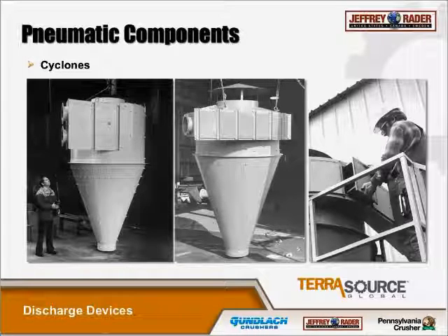These cyclones, just as with the valves and the elbows, are designed to have a low impact inlet section that allows you to minimize material damage, eliminate buildup, and get longer service life, easier maintenance, all the important things. Got different options. You can do multiple injection as shown in the photograph on the left. You can do right hand, left hand inlet. You can replace body liners, though most people just choose to replace the entire cyclone since they're comparatively inexpensive.